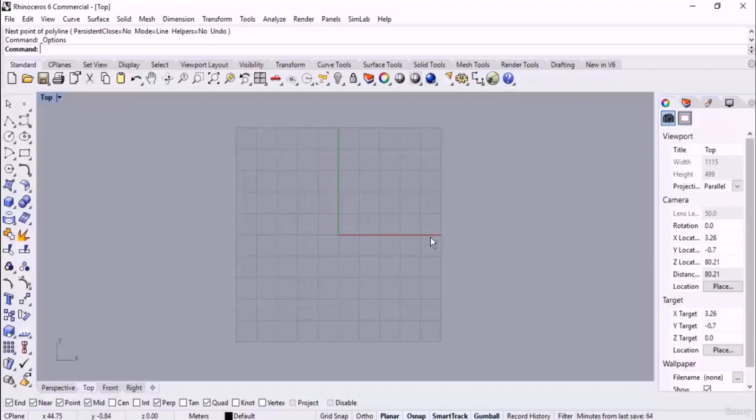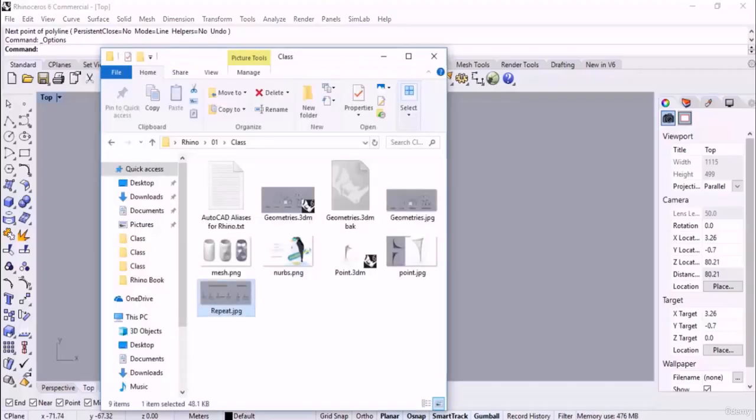But another important thing or technique is setting the Rhino shortcuts. In fact, Rhino is a CAD-based software, so it has many similarities with AutoCAD. In Rhino, we are provided with a capability that we can transfer all of the shortcuts from AutoCAD to Rhino. If you have been typing TR for trimming, we can type TR in the command line for getting access to the trim command. We can add the CAD shortcuts to Rhino. But how can we do this?